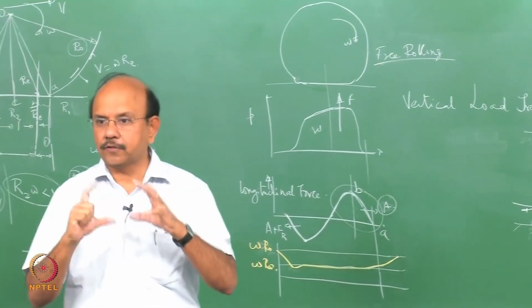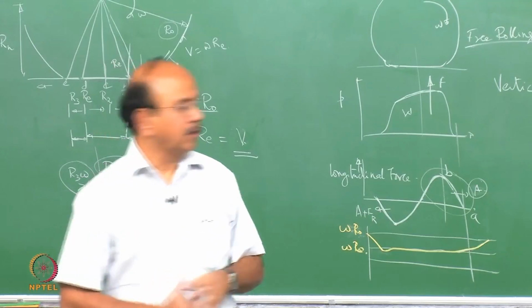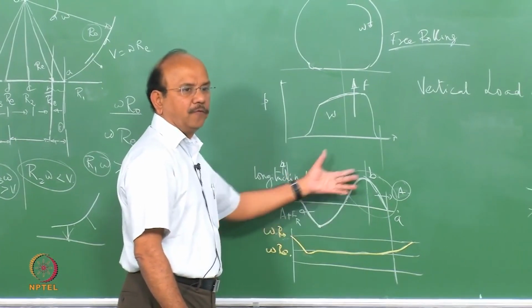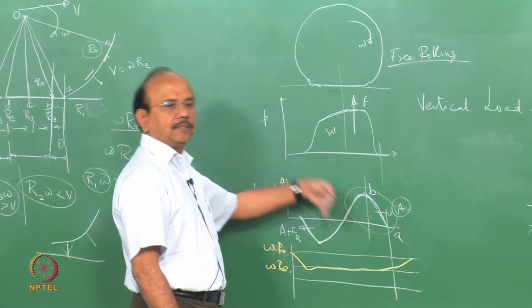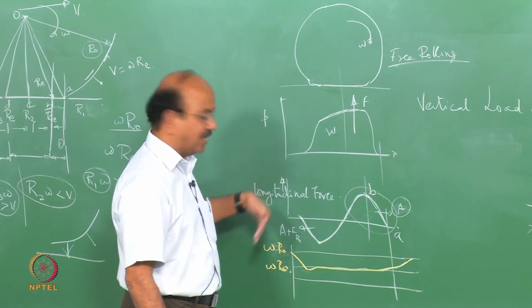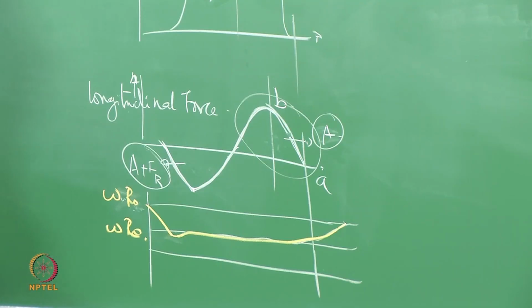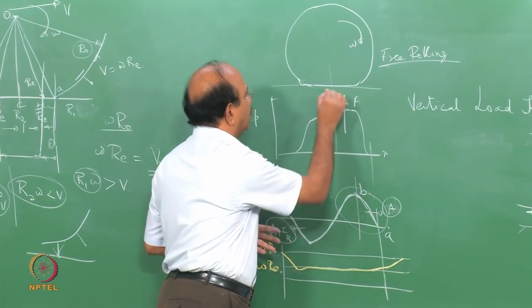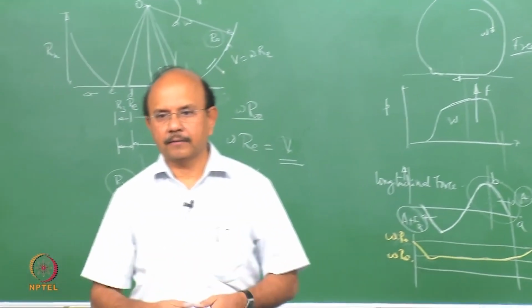So all the viscoelastic forces come into the picture, and the loading curve is not the same as the unloading curve. So if there is a force A in one direction, the sum of the forces behind the contact patch has to be A plus a rolling resistance force. So in sum there is a difference, and that results in a rolling resistance force Fr.